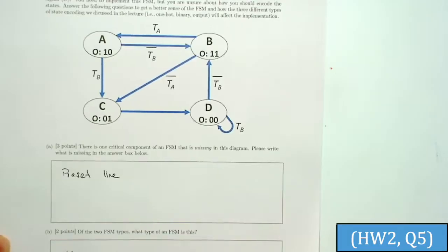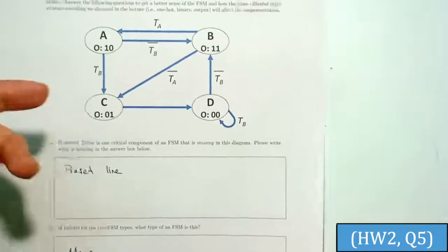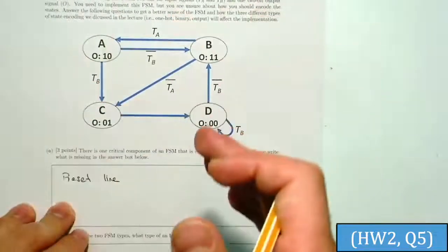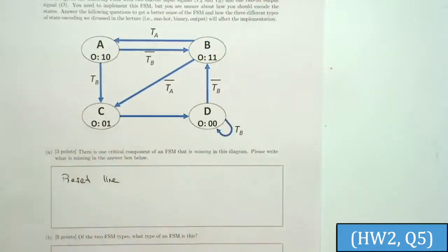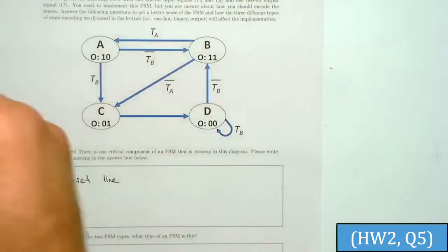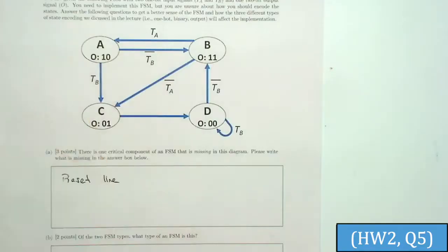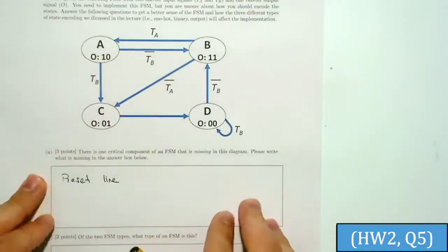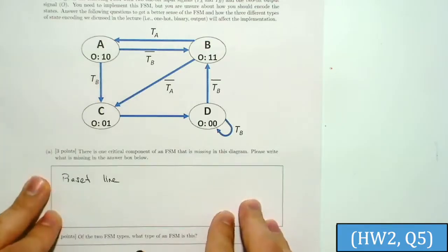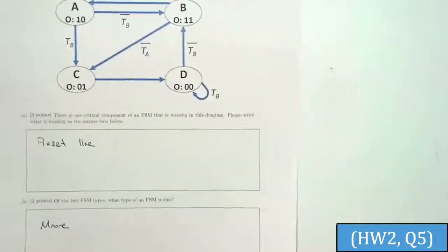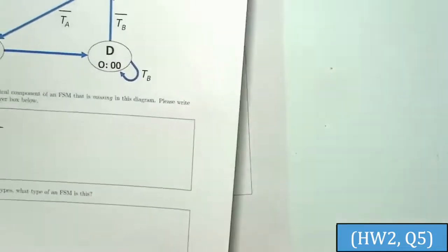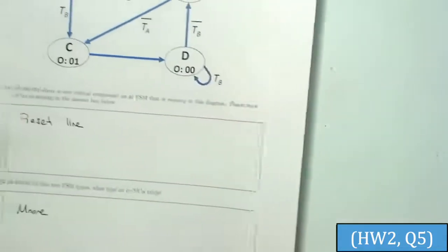So for the representation, yeah, you can say that this is our initial state, but to really have it as an initial state, you should make sure that when you start this FSM, it's really going to be the initial state, right? So how do you ensure that? You need to have some sort of reset line so that it goes there when you reset, and then you start it at the initial state. So basically, it means the same thing, to have the initial state and the reset line. Okay. Any questions related to those? Okay.